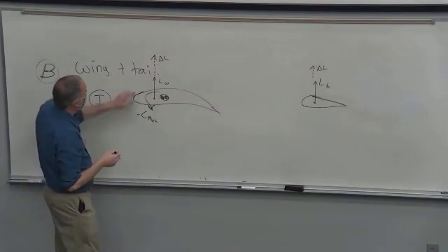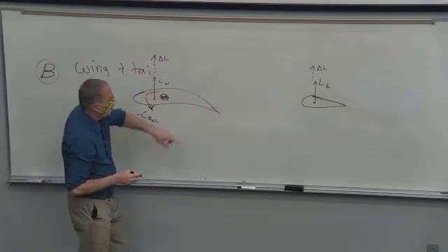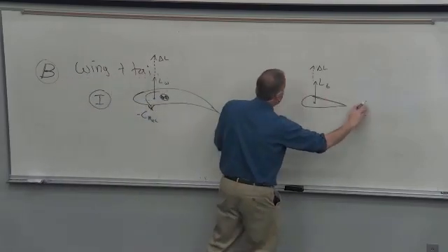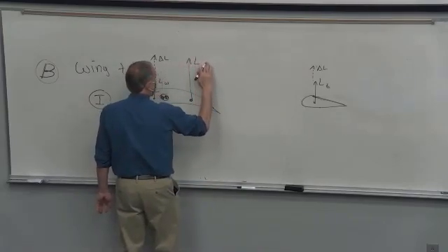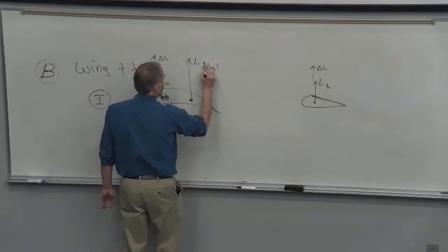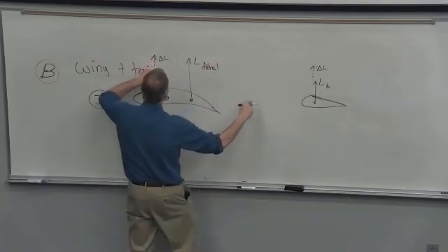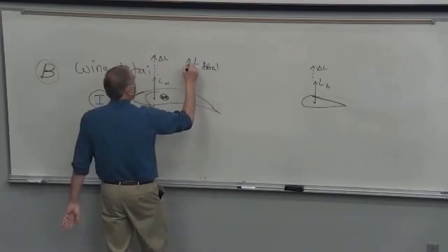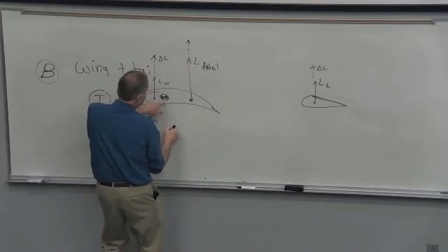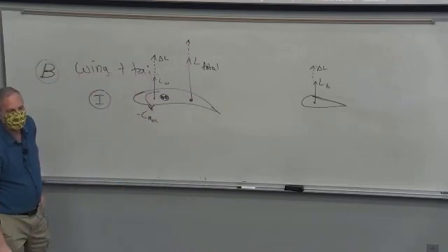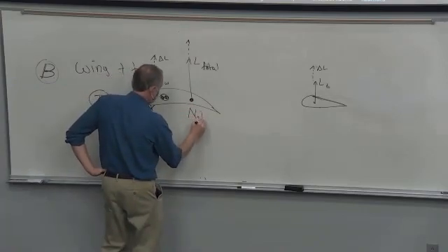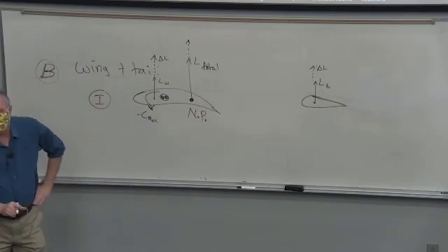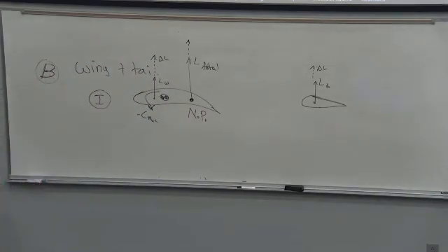And what really matters is where is the net resultant of the lift, right? We've got to make this big enough and far enough back that the net resultant of the lift, the total lift, adding the lift of the wing and the lift of the tail, when these deltas happen, you get it acting behind the CG, and that's what gives you the stability. And in fact, we'll have to find this point here. It's called the neutral point. We'll define that more precisely later on. But we want to make sure that that's behind the CG so that we do get that stability behavior.